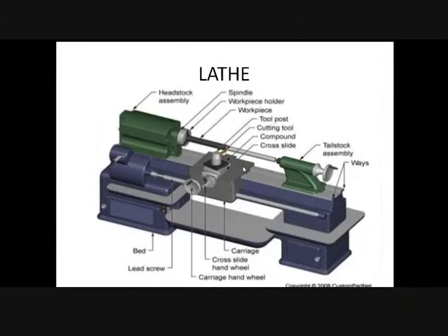In lathe bed, there are again four subtopics: what are the functions, what is the material used, what are the manufacturing methods, and what is the shape. We'll start off with functions now. The functions can be rigid, damping, or house. It should be rigid enough to withstand the forces acting during machining and different elements of the machine tools. This is called rigidity.